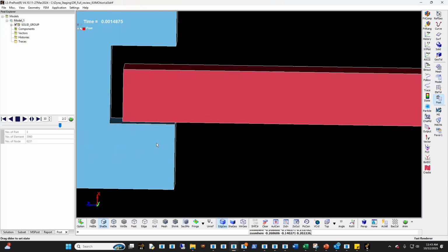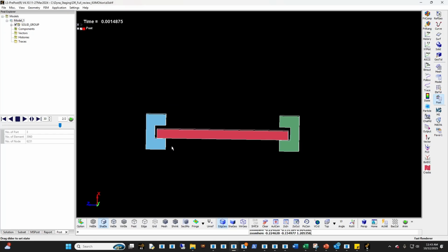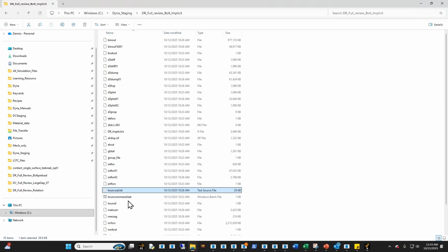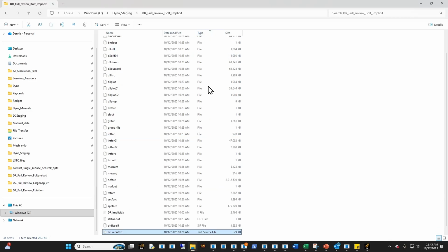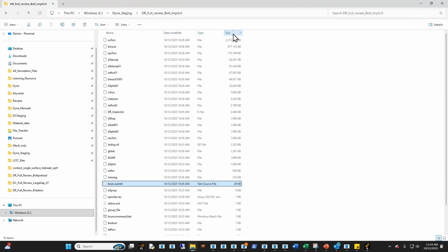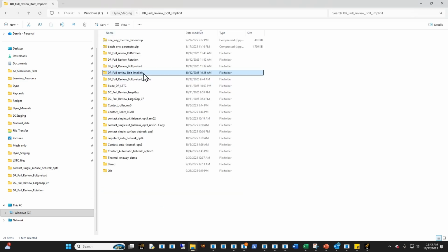And that's what DR did. It's going to look at the distortion KE versus the peak distortion KE. When the red plate hits the slot, the KE is going to go down, and that's when you have convergence of the dynamic relaxation. So it's a very good way to kill any rigid body motion in the system. So if I were to show you the